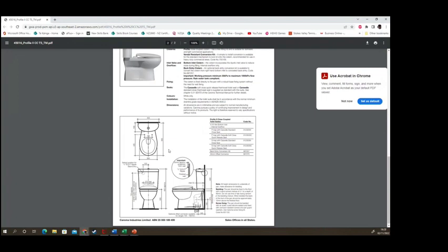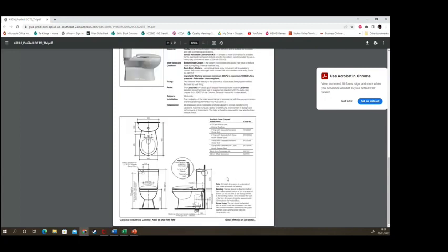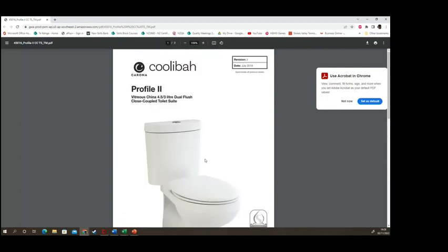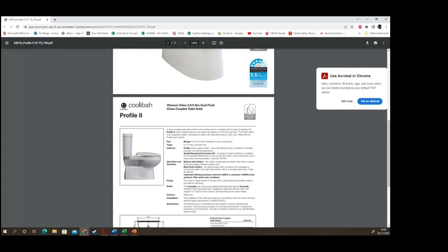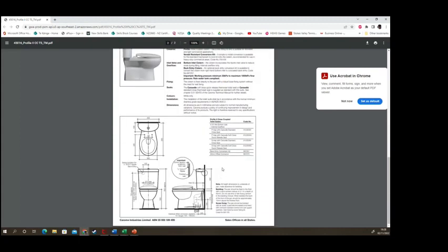And likewise, if you're going to maintain it, there's only a couple of things that can go wrong. The underwater washer that seals it when it's full up and you haven't pushed the button, and then the water inlet either needs adjusting, or the washer can fail over time as well, and it keeps filling up regardless of what's happening with the flow. So that's a basic Caroma system, close coupled like most toilets seem to be these days.